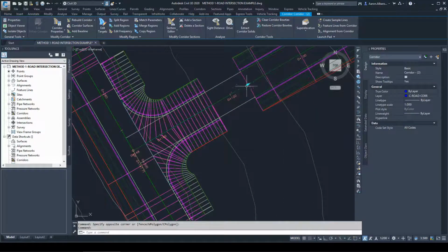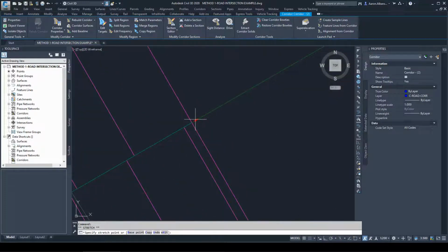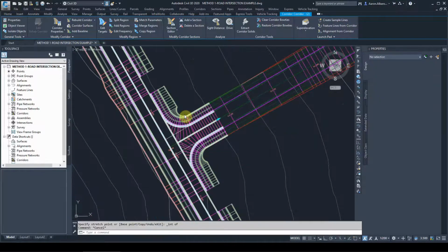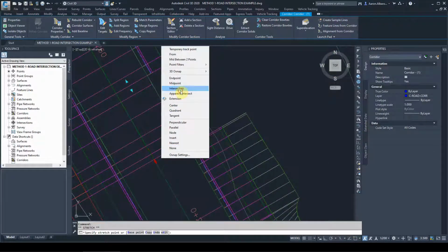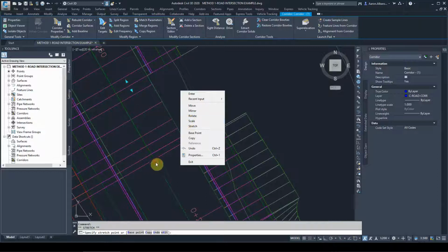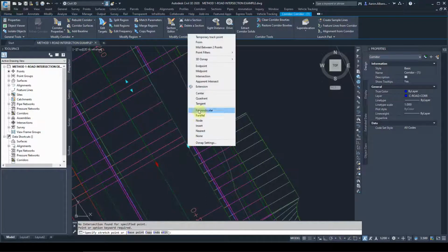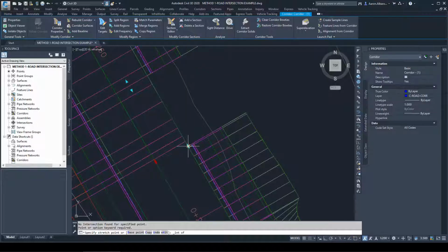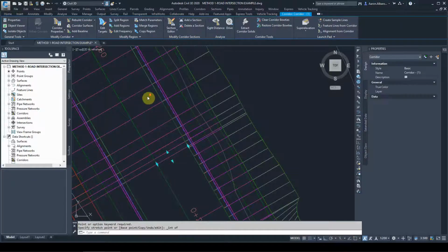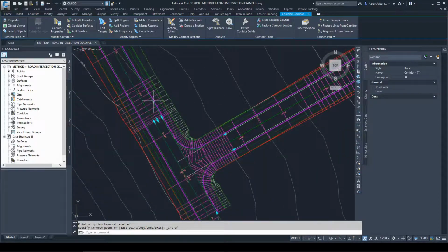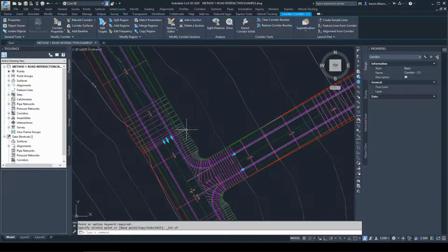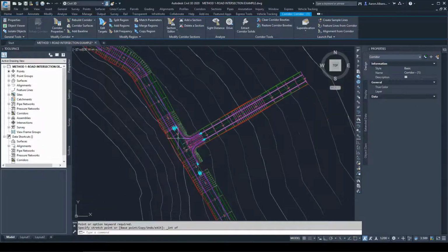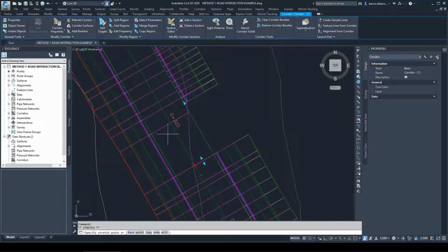All we have to do now is just slide this corridor back in place and make it meet the other corridor so we can complete our road. And I can slide this one back here for the regions and again make it meet. Shift right click intersection of this area here. A good indication that your work is accurate is when you see the daylight connected seamlessly between the existing corridor and the new corridor that you created around the intersection. We'll do the same thing here.